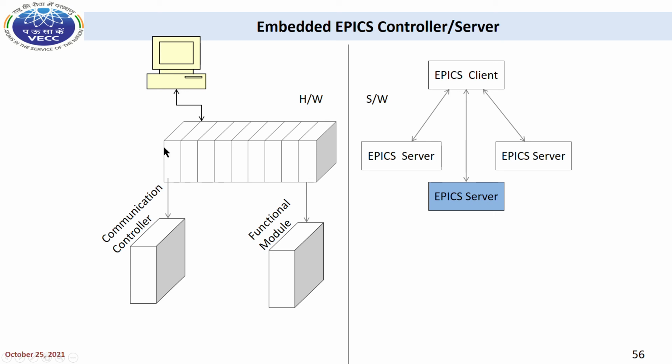And these modules are connected over a backplane. The different modules are digital I/O, analog I/O, precise current measurement modules, stepper motor and DC motor controller drivers, and readout for various optical encoders. Some modules are intelligent, and local group control running is possible.